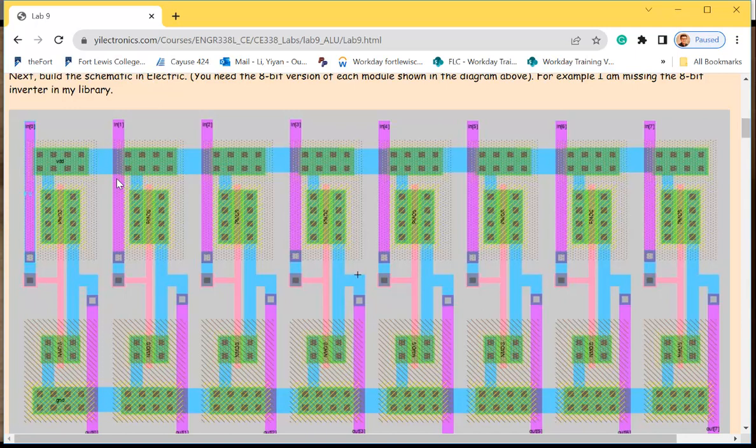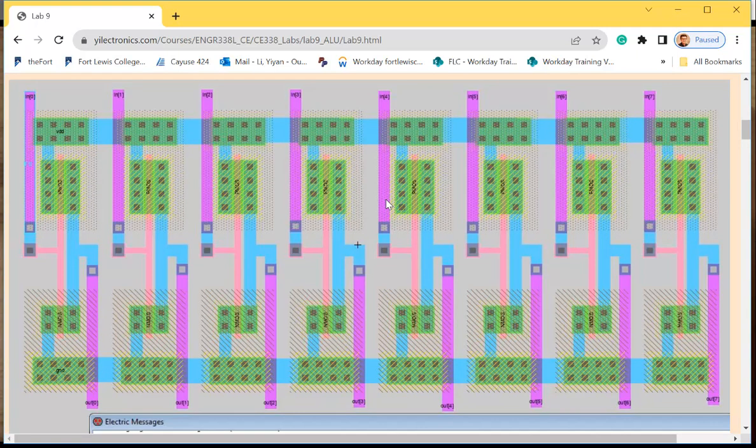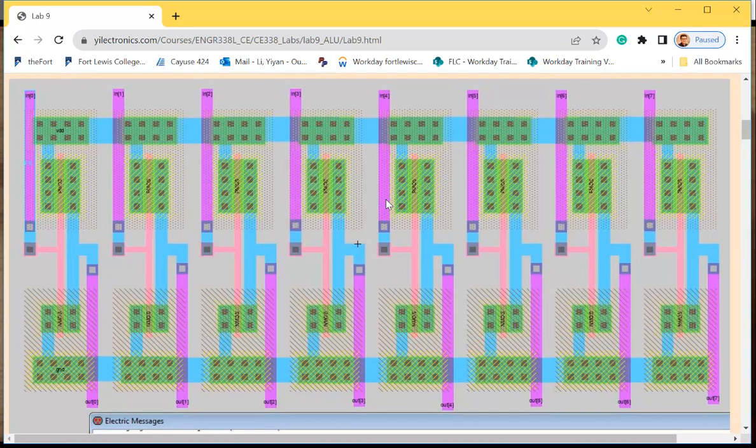But still, for good practice, you should cover everything physically within the same well, because that's the same voltage node, that's the same VDD. So you should connect them to the same VDD. They are shorted together, right? If they're not shorted to the same voltage, for example, if you have two different power supplies in the circuit on the wafer, then there can be many different cases, but they can be in different wells because they have different potentials, right? So what about these ones?